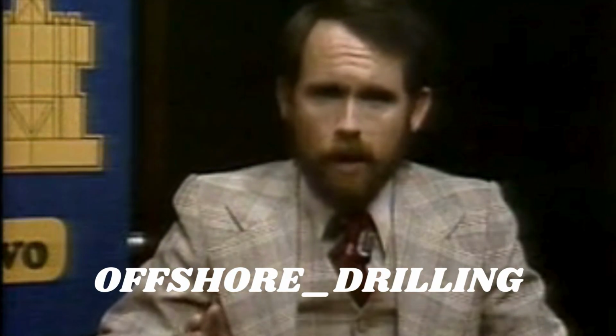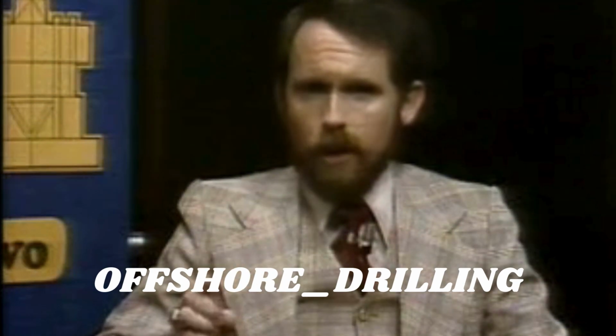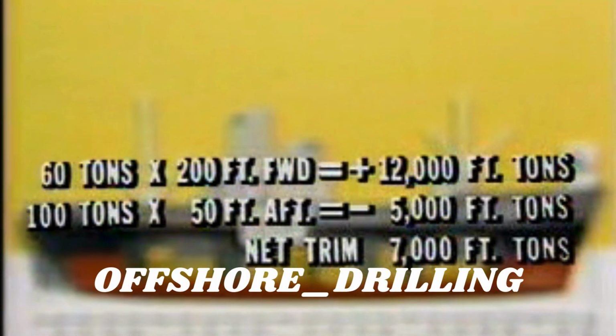Let's assume in this problem that MT1 for a mean draft of 14 feet 4 inches is 1,000 foot-tons per inch of trim. Since we loaded 60 tons 200 feet forward of the tipping center, we have a positive moment of 12,000 foot-tons. Now, since we loaded 100 tons 50 feet aft of the tipping center, we have a negative trimming moment of 5,000 foot-tons. Combining these two, we obtain a net trimming moment of plus 7,000 foot-tons towards the bow.